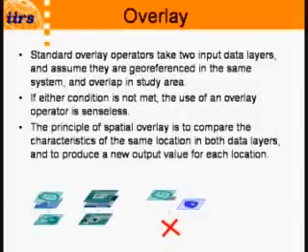Now if you apply standard overlay operations, the most important thing is your data should be on top of each other. That is, they should have the same projection and they should sit on top of each other. But even if they overlap to a certain extent, they can be overlaid. It is not necessary that their extent should be exactly the same. Their projection should be the same and their extent should overlap at some place. Then you can do any overlay operation. But if their extent or their projection doesn't match, then it is not possible to run an overlay